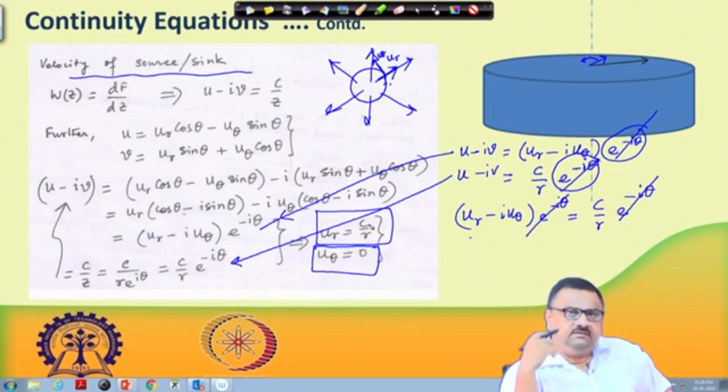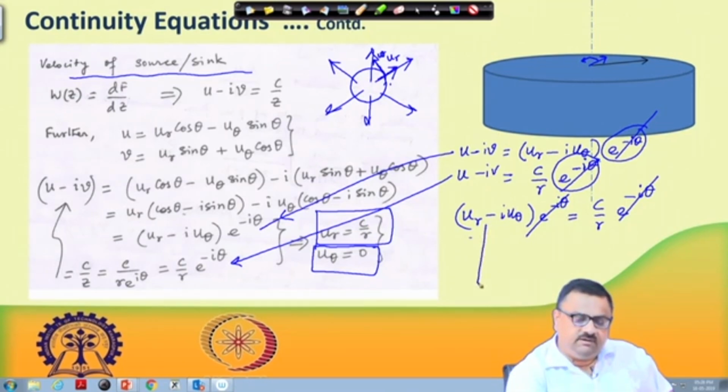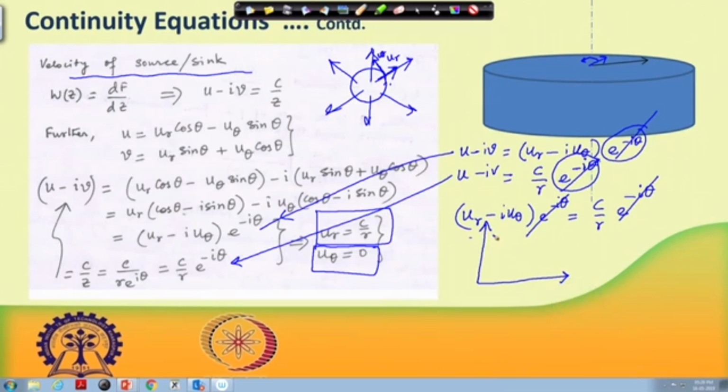This in fact makes perfect sense, because you remember when we were trying to solve this Laplace equation for pressure in a cylindrical system, working only with r and ignoring theta and z, we said that V r is proportional to 1 by r. Mod of V r has to be proportional to 1 by r.